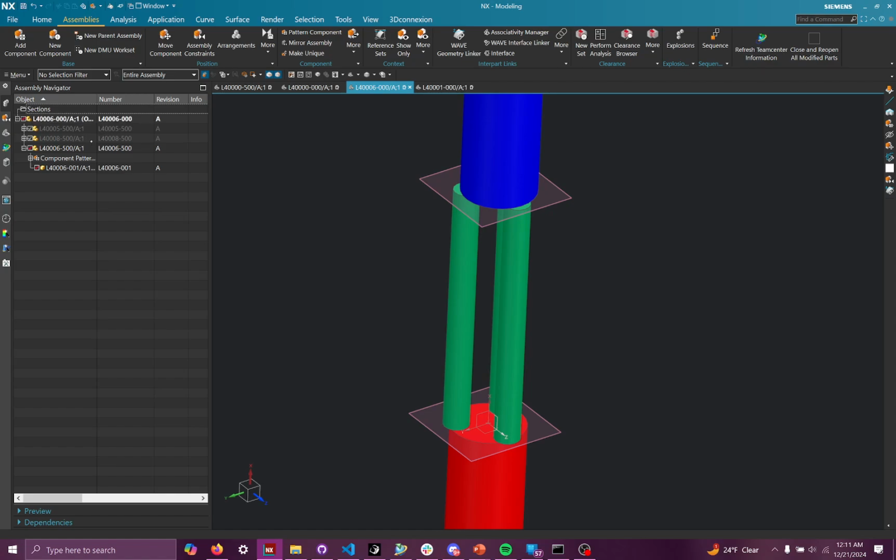It's a little abstract, so it can be a little hard to explain, but since the layout file contains the assembly file, if I load the layout file, I don't think it necessarily loads the assembly file, but it is able to update the assembly file via the load inner part data.